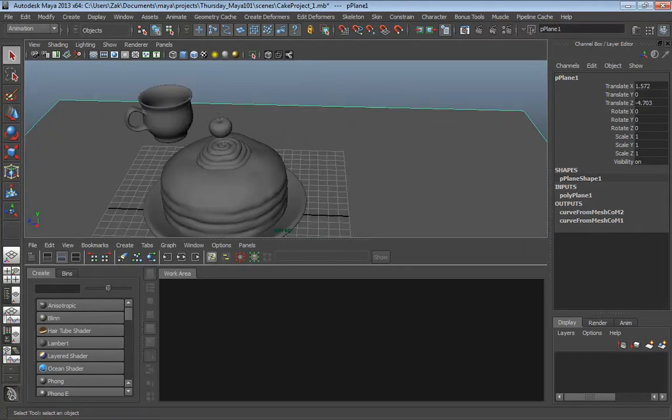And Engage just asked if you did that sort of scaling, wouldn't you stretch pixels, i.e. ugly? One, yes, you would stretch pixels. Whether or not that's ugly is a long story. I mean, it could be depending on the resolution of your texture, depending on your needs at the time. Like, for instance, I try to discourage people from just automatically creating big, 1024, 2048 textures for every single thing they need. Take the extra time to consider what objects are really important in your scene. I mean, and the more you get into creating your own materials and textures, the more important this will be, and you'll see that.